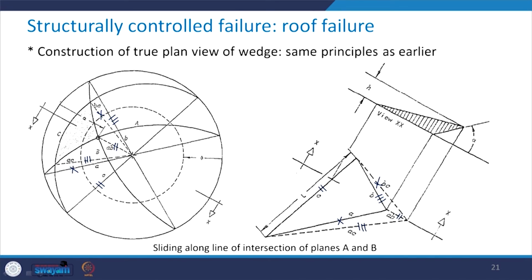And then you know that this length you can obtain L, which is the trace, and you know this angle alpha. See, this intersection AB is there, and from this outer circumference you measure these angular divisions in order to get the value of alpha, rotate it here in this particular fashion, and you will be able to obtain this H.